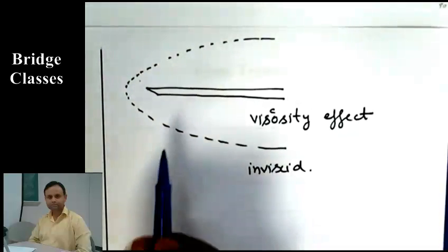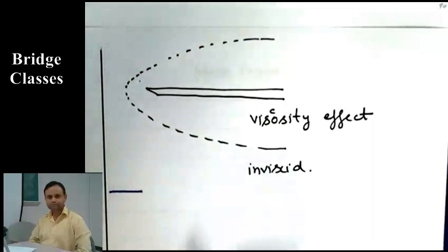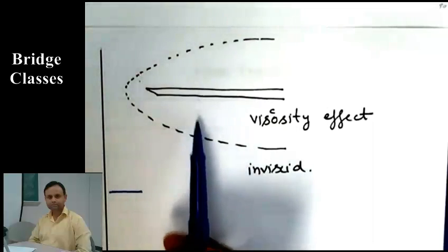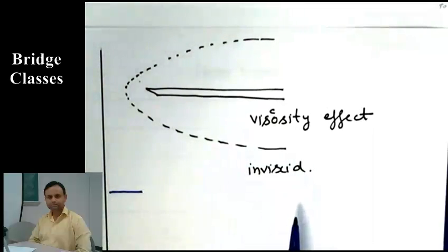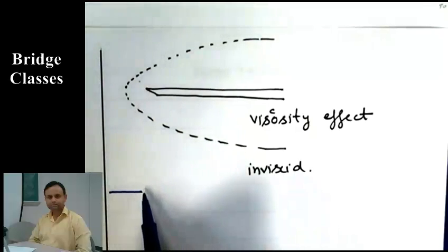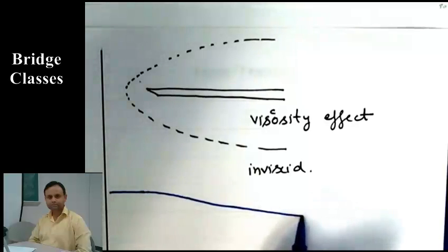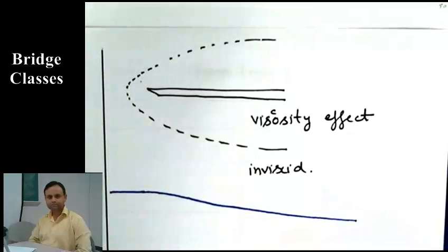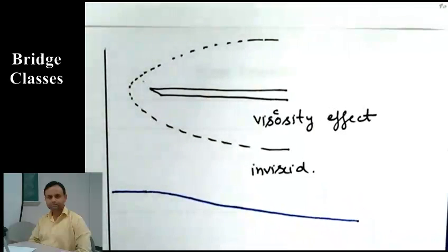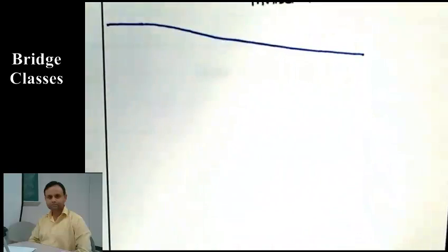And if you want to draw streamlines, say a streamline here, the flow is in this direction, but because of the boundary layer, there is deflection of the streamline, you know that. In this case, because the boundary layer is thick, the deflection will not be negligible, it will be substantial. Whereas if the boundary layer is thin, the deflection of this streamline is very small. It almost goes straight. So that is the idea. So this equation is important. We got this boundary layer thickness.